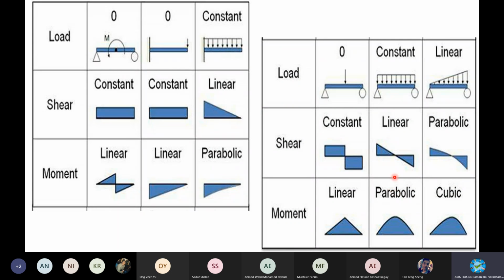You see here, exactly, the maximum bending moment occurs where the shear force is 0, right? The maximum bending moment occurs where the shear force is 0. No loading, so it is free to move. And then parabolic. For this video, this linear type, I don't emphasize too much on this. Triangular load, I am not giving you in this session. Let's understand these two types well versed.